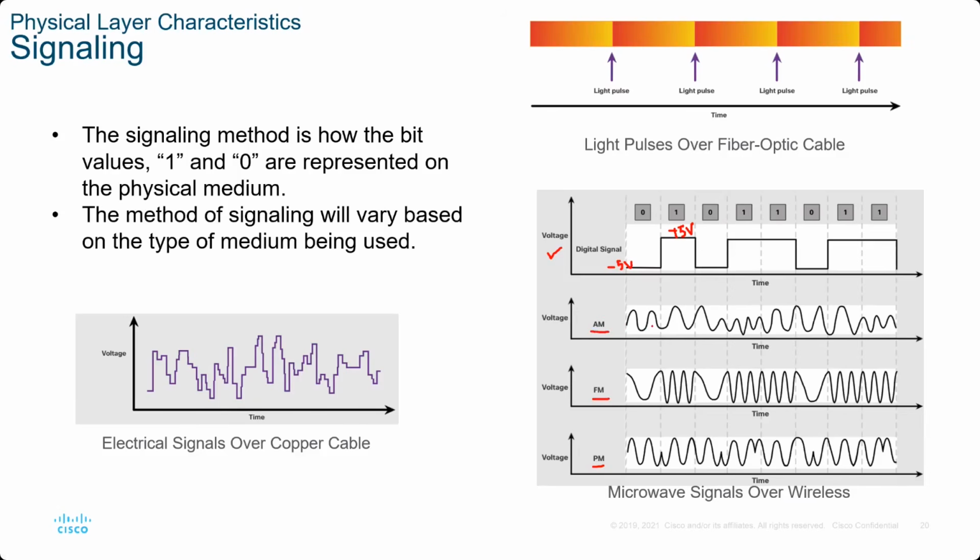You just need to know that zeros and ones can be sent using different methods. In amplitude modulation, if you have a lower amplitude of a signal, that would mean it's a 0. If it has a higher amplitude, see here, then it would mean 1. So lower amplitude 0, higher amplitude 1, and so on. This is how you can send it.